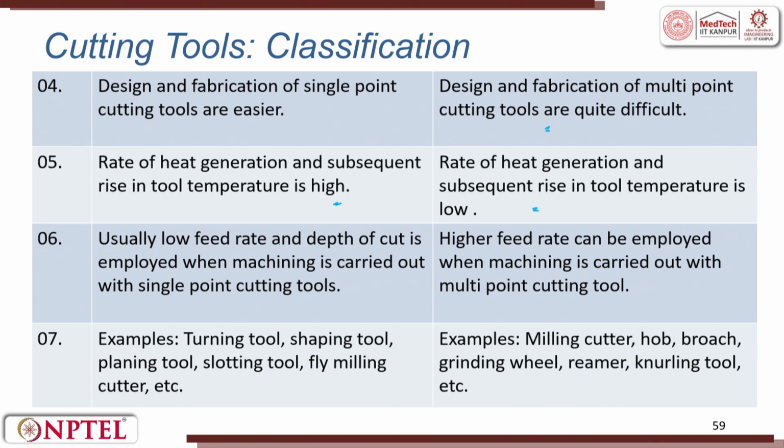Usually a low feed rate and depth of cut is employed when machining is carried out with a single point cutting tool. Here we go with a higher feed rate and higher depth of cut. So, under this classification of single point, turning, shaping, planing, slotting, fly cutting, fly milling cutters, boring, etc., come into action. Here, milling, hobbing, broaching, grinding, reaming, all these things come into action. So, single point and multiple point classifications are given here.